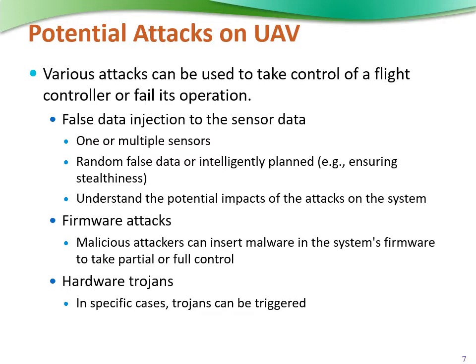The existence of a hardware Trojan is hard to test or validate. As I said, it is a special circuit that is triggered often only in rare cases. So from the input and output of a device, it is hard to understand whether it has any hardware Trojan. Once it is triggered, the on-time and off-time of a PWM signal can be maliciously modified to result in undesired behavior.